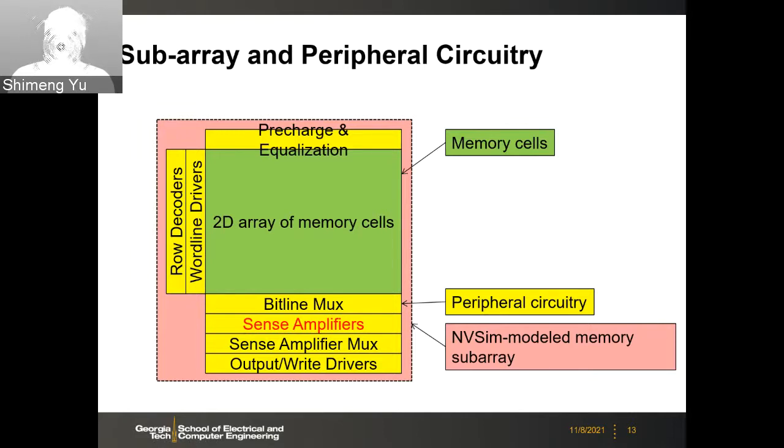If you look at different memory cells and different memory arrays, they look pretty similar. You don't have too many choices. For the sense amplifier, this is where most innovation happens even today. If you are hired as a memory circuit design engineer in a company, you spend most of your effort on the sense amplifier, because it depends on specific technology and your design targets.